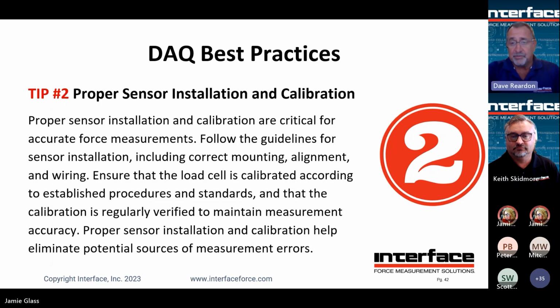Calibrations. Again, follow the manufacturer's guidelines for calibrations. With our load cells, we typically recommend once a year. However, if we know ahead of time, we could do things to bump that out to 2 times or once every 2 years, or in a lot of systems, maybe your requirements are going to require you to do it more often. I've seen situations where customers are required to do a calibration before and after every single test. Next slide.